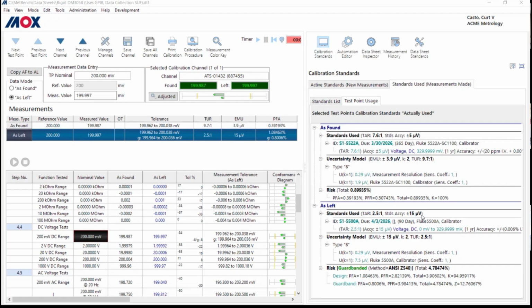Another thing you can do is the uncertainty budget. A lot of times when you're doing a calibration, you may not know the uncertainties until you're actually doing the calibration. You may be using something like thermal converters, or something where you've got a reference, or SPRTs, that kind of thing, and you're going to use information from their actual calibrations.